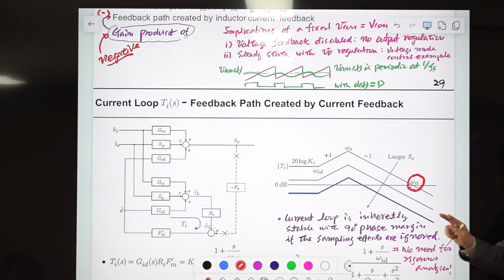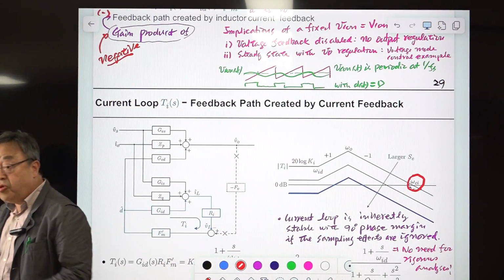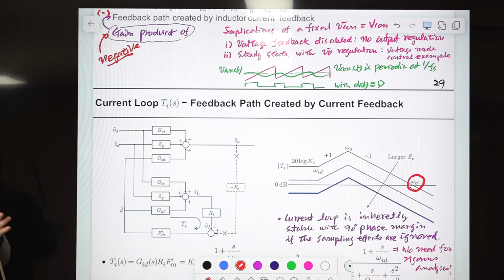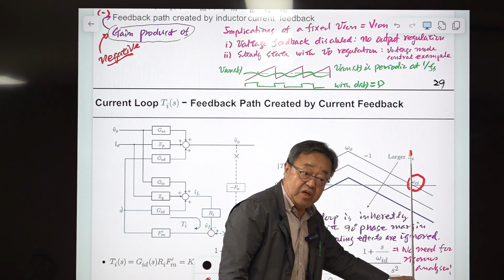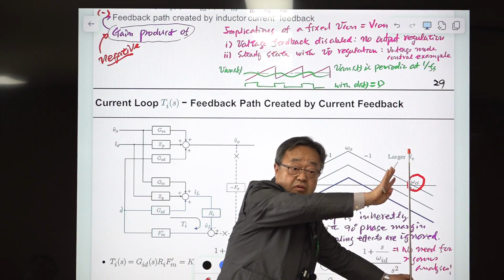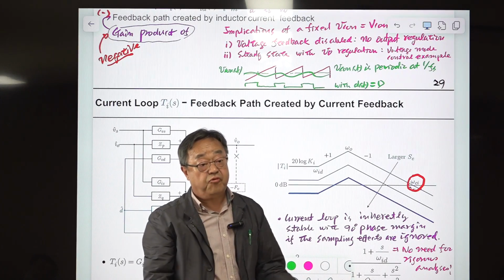Okay? That is the way of doing all the business without any trouble in classical analysis. You understand this? Classical analysis is ignoring the sampling effect totally. Still they are okay because they have a hard restriction, a limit: don't go in the neighborhood of the Nyquist frequency. Then you are still fine.